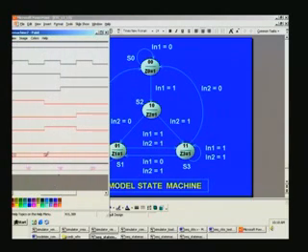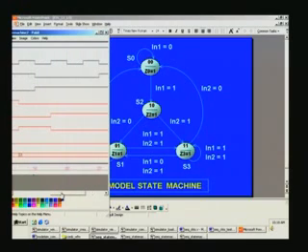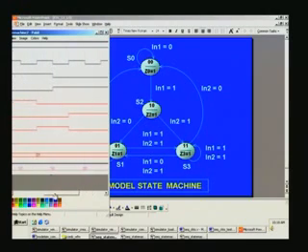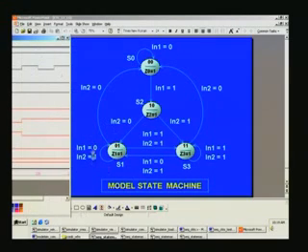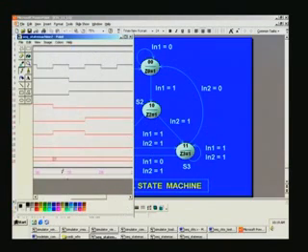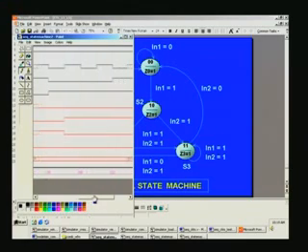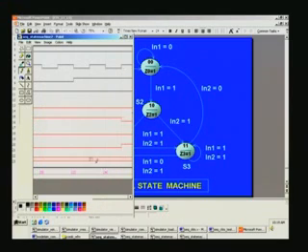Next we will go from the 0 1 state. So that is in the 0 1 state, and these are in1 and in2. In S1 state, in1 is 0, this is 1. So long as it is 0 1, it continues to be in the 0 1 state as per this. On the other hand, if in2 is 0, let us see what really has been put. This is what you have. It continues to be in the 0 1 state, and here it is going to the 1 1 state.